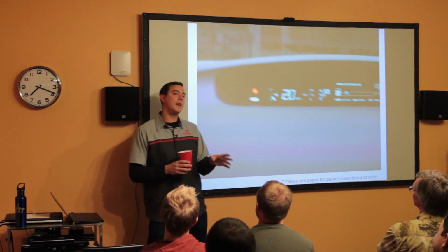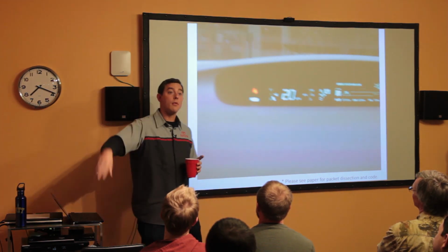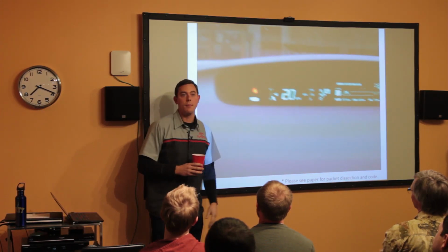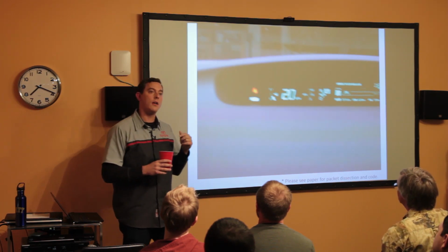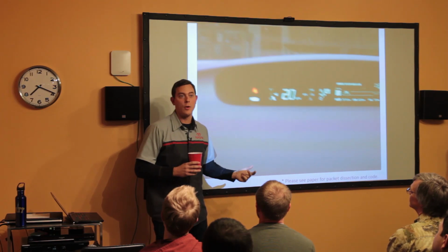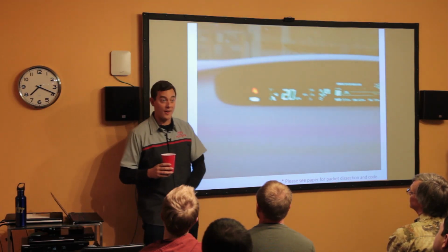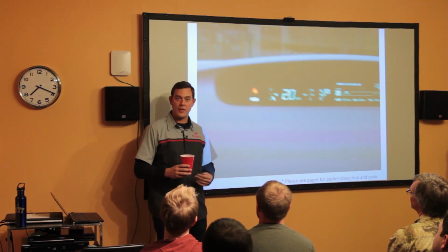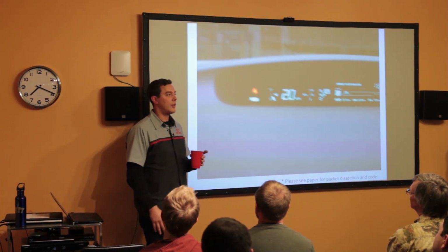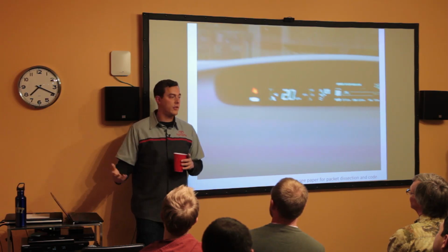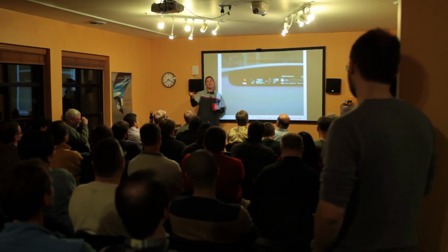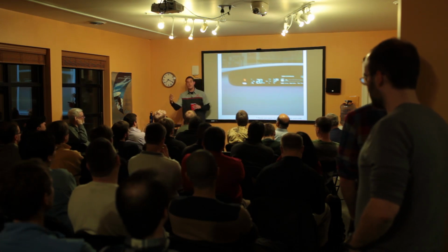So here you have to think about this. When you're sending messages out on this broadcast network, not only are you changing it for the display, but anything that was dependent on doing something with speed was notified that you were going 20. That's why it said, hey, put your seatbelt on, because it thought I was going 20 miles an hour, because that beep doesn't come on unless you're going above 5, right? So it doesn't annoy you. So not only when you send these type of messages are you changing one thing, but there's a lot of collateral damage that happens from anything that's listening for that ID in the messages that you're forging.